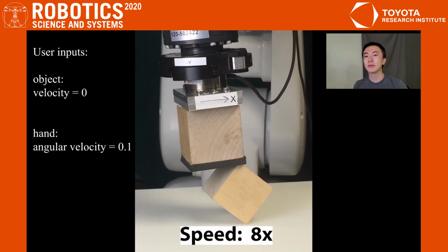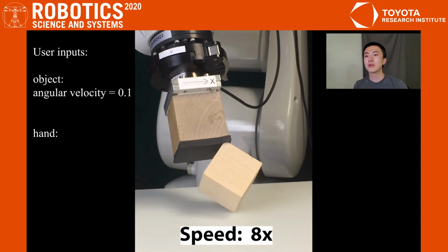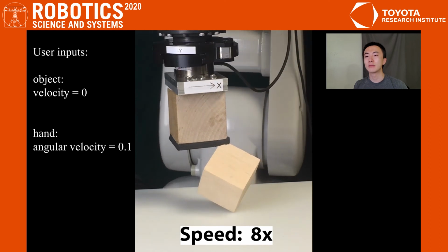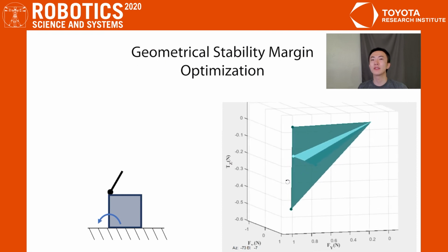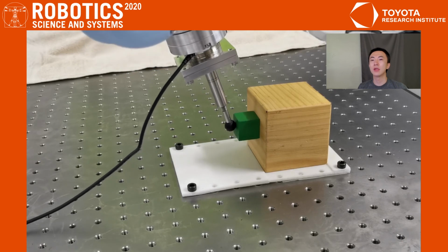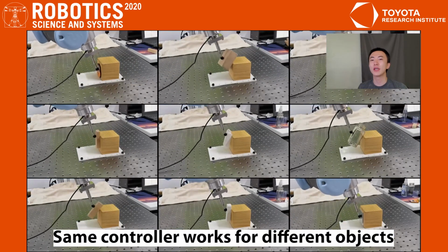At each time step, the user only needs to provide the desired velocity. Our algorithm selects the contact mode and computes the control to maximize robustness. We can also use the stability margin to find good finger placements by optimizing the contact geometry over the geometrical stability margin. This approach further improves the robustness of the control. In this example, the same controller works for objects that are different in shape, weight, and friction.